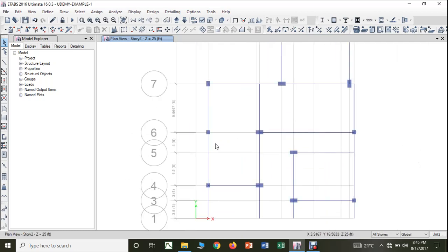So this is perfect, no doubt, because here as well as here the column lengths are of larger line, so this is okay, but this I have to change. Okay, so this I have to change because this is of larger length compared to this, so both the loads will come here, and even this will create an eccentricity here, therefore I will change it to this orientation.